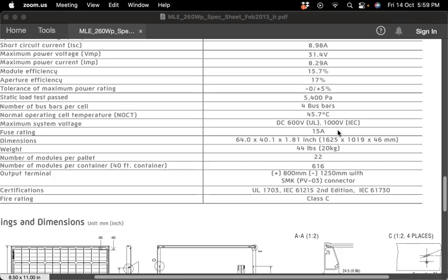If, for example, we go to upper Egypt, far into Aswan, or maybe deeper, going into Sudan, or to a very hot area where the temperature is normally 45 degrees Celsius, then in this case you will find the operating cell temperature of your solar cell reaching 65, 70 degrees, because again it's 10 to 20 degrees higher than your environmental temperature.